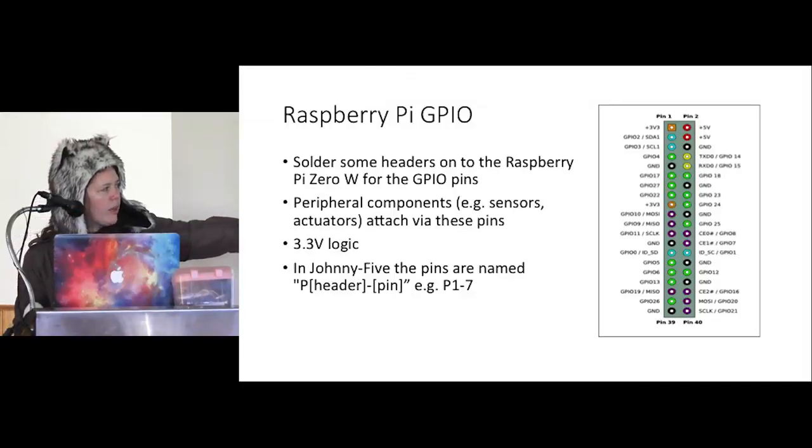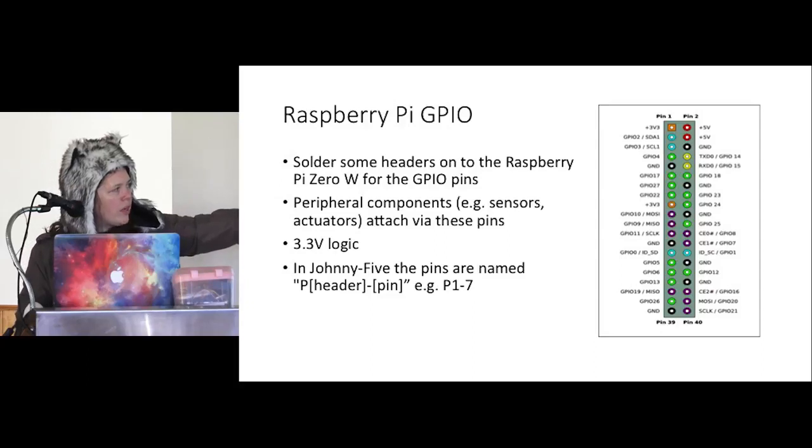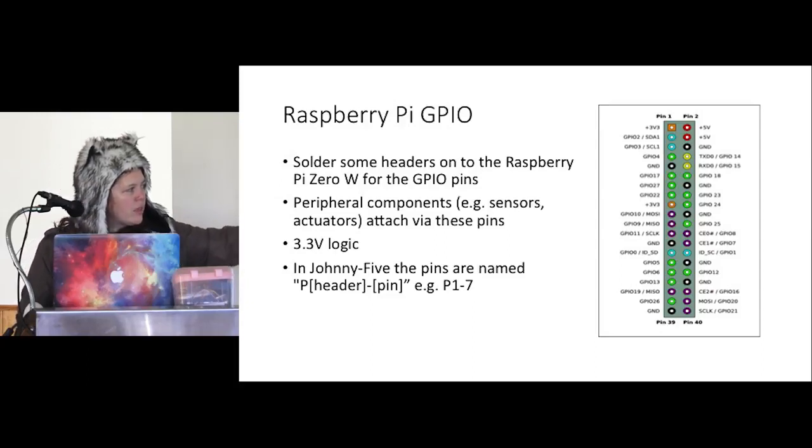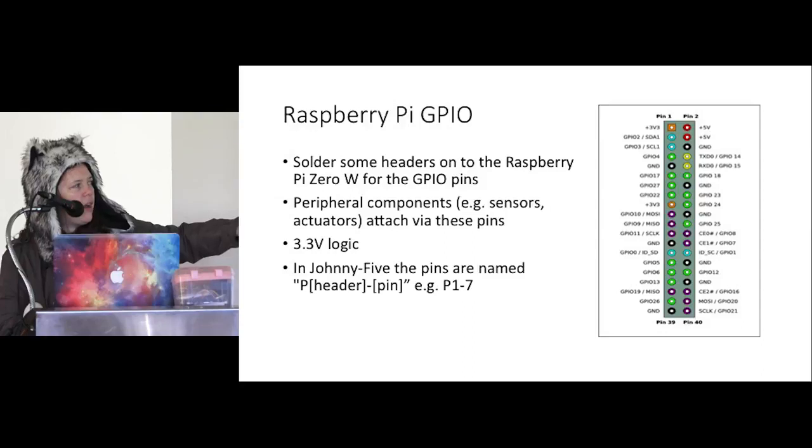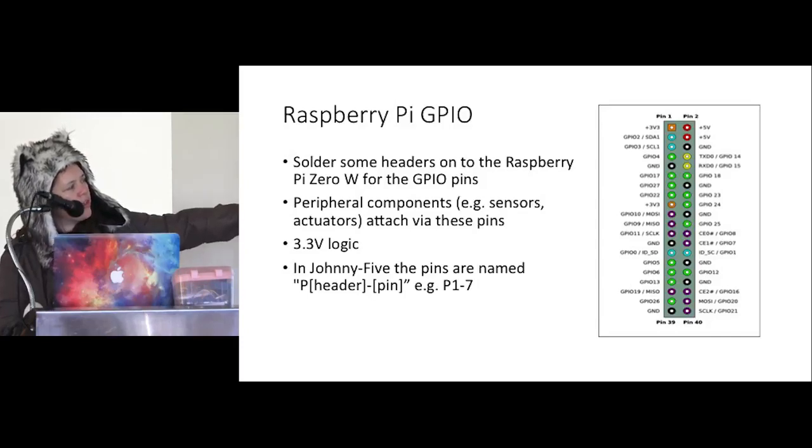So what we've got here is the pins on the Raspberry Pi. If we go back and look at that diagram there, we're connecting to GPIO 7 and we're connecting to ground. That's the fourth one down on the left-hand side and the third one down, I think, on the... Oh no, hang on, GPIO 4 is what we're connected to, sorry, and ground. So I've got one jumper wire going across to the LED and the other one going across to ground.